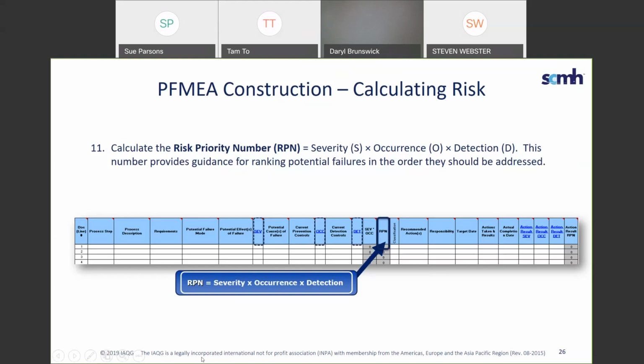And people ask, well, what is the threshold for your high RPN? Again, the rule of thumb has always been that a triple digit number or higher is something you want to investigate. I say you can't work on 15 things at one time, so you want to take the top 5 or 10, work on those if they're grouped, and keep working them down.